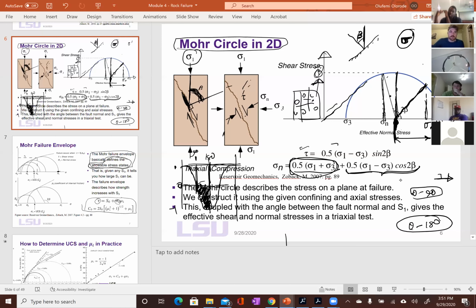Isn't that the reason we don't use the uniaxial test, because there are pre-existing cracks, but the compressive stress has kind of closed them? That was a fuzzy explanation in module 3 that I didn't get too clearly. Yes, but those were more on micro cracks. Those were very small cracks where it's going to be reversible, right? If you have major cracks, then it's not going to be reversible no matter what you do. You can't just close it. So those are limited to micro cracks.